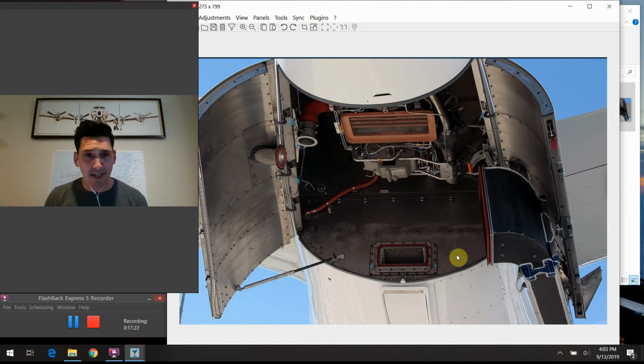It is as follows, and it's kind of a lot, so I'm going to say it kind of fast, but I'll try to include it in the comments, or the description section on the bottom of the presentation here. The conditions are a fire, if the air inlet flap is closed, an overspeed condition, no acceleration on startup, a slow start, EGT over temperature, no flame, reverse flow, low oil pressure, high oil temperature, DC power lost, overcurrent, sensor valve, IGV failure, ECB failure, no speed, underspeed, loss of overspeed protection, oil system shutdown, inlet overheat, clogged oil filter, and loss of EGT thermocouple.